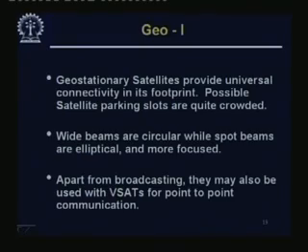within its footprint it provides universal connectivity, from any particular point you can communicate with that satellite, and possible satellite parking slots are quite crowded. Wide beams are circular, while spot beams, which are more focused, are elliptical. Apart from broadcasting, they may also be used with VSATs for point to point communication. We will come back to this point later on.